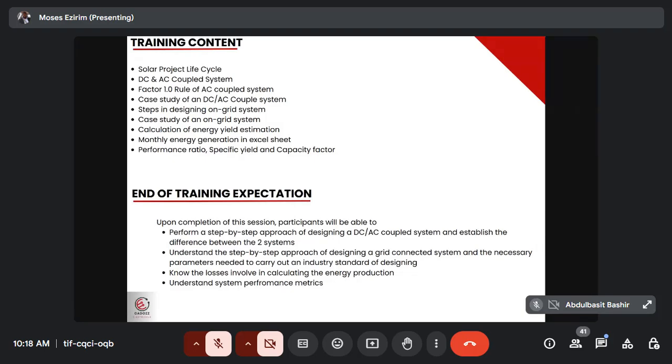Once you've done that, you factor in a lot of things. Check if there is going to be shading where you're going to put your panel, whether roof mount or ground mount. Identify the orientation, and identify how you are going to move in your equipment, because during installation, you need to factor in if there is going to be space for trucks to pass through. If there is not, you need to see how you can make a way. Those are the factors that you're going to see during assessment.